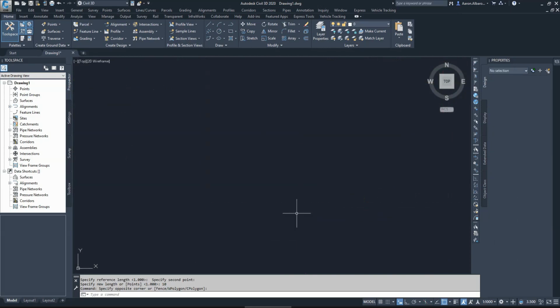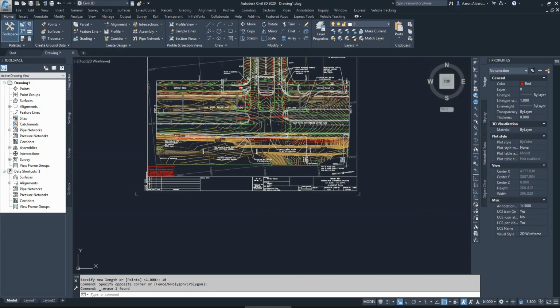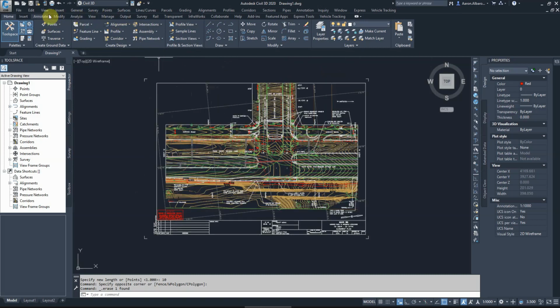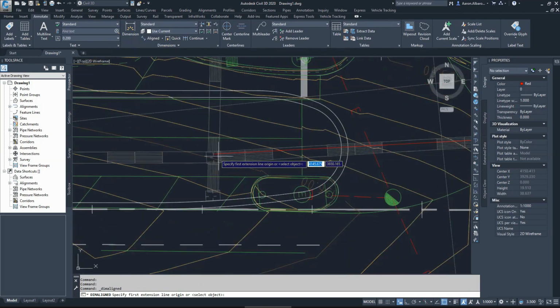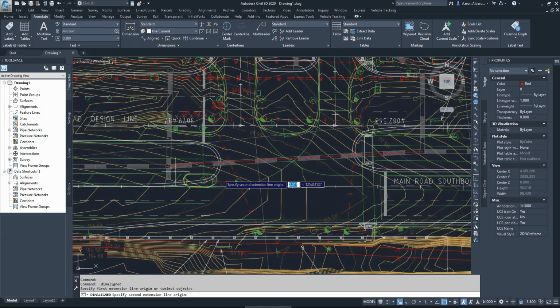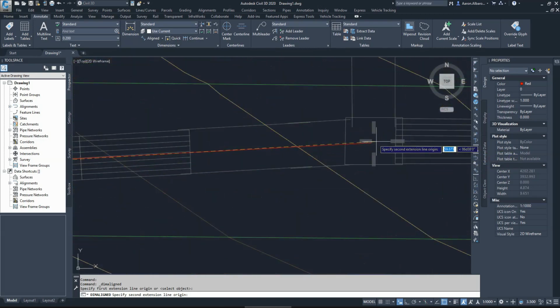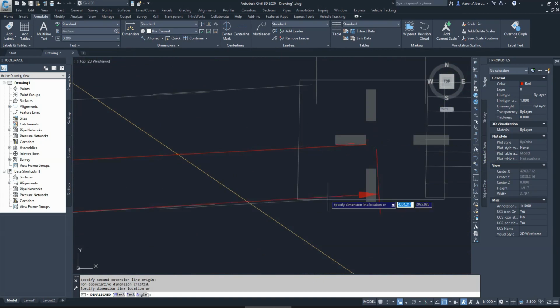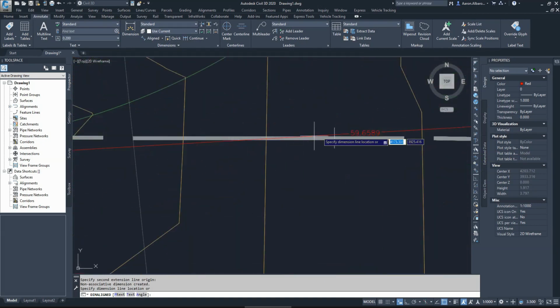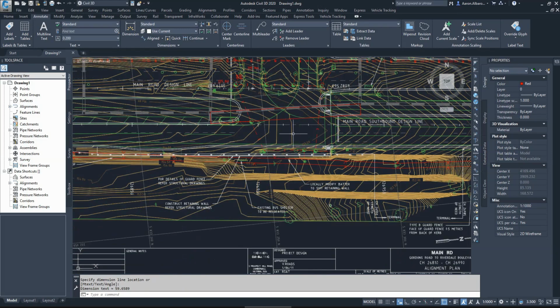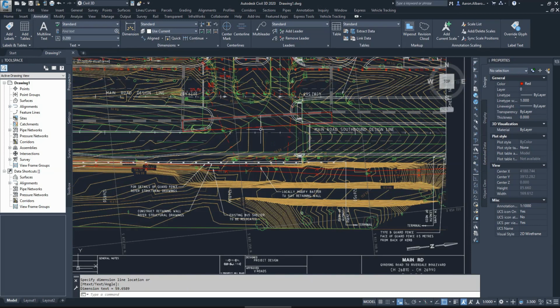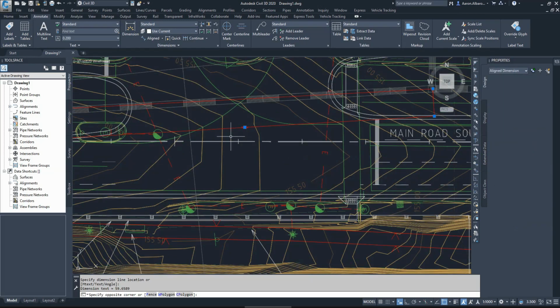Okay, now if I did that, that means everything here is to scale correctly. In other words, if they were asking me, that takes obviously a few seconds when you are good at it. So again, if I go back here to measure that pipe length, choose the line length, and let's say they ask me from the center of that intersection to the center of that intersection here, roughly to here, that will give us about 60 meters. So there you have it. This is how we scale things on scale plans on Civil 3D or AutoCAD.